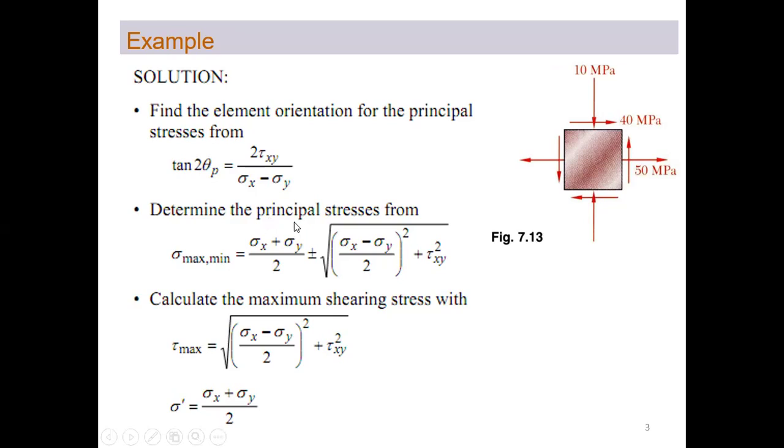And this analytical model is used to determine the stresses along the principal axes. It would return two values, one with the plus sign and the other with the minus sign. With the plus sign, it would return sigma maximum, and with the minus sign, it would return sigma minimum. Next, part C, which you have to find out.